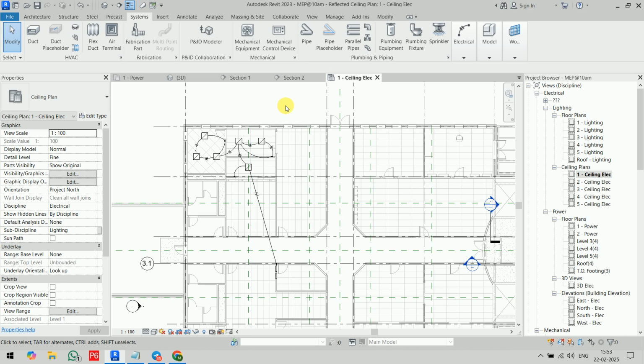To place all those components, first you have to load them from the library. We will place them and connect all those components with the fire alarm control panel, the FACP. First we will learn how to place all the required components. Then we will connect them with the FACP, and first we also have to place the FACP.